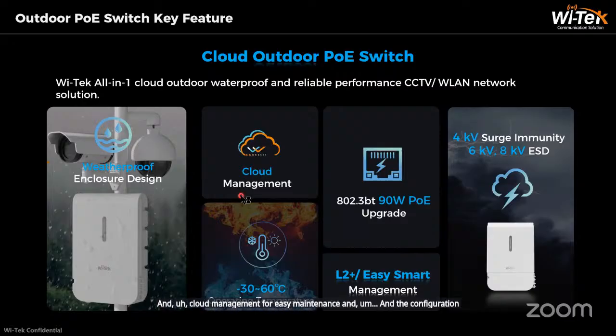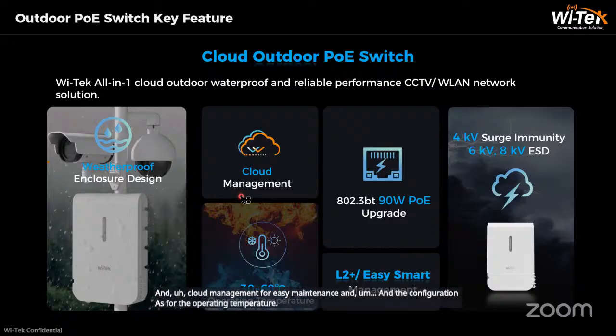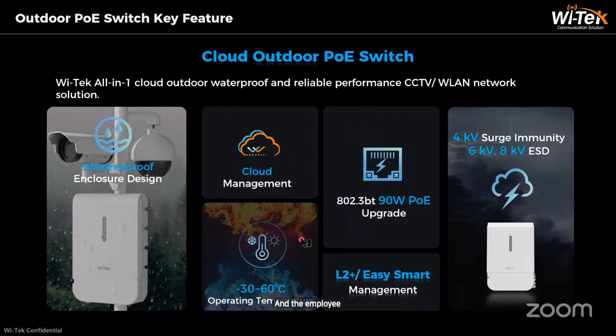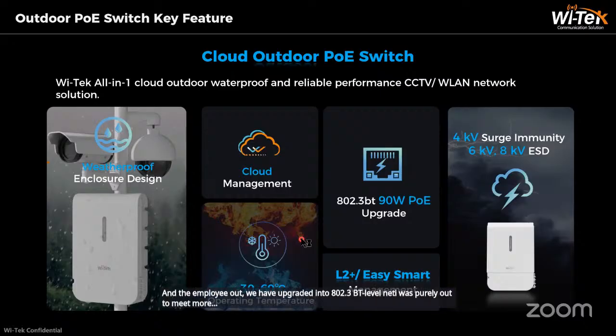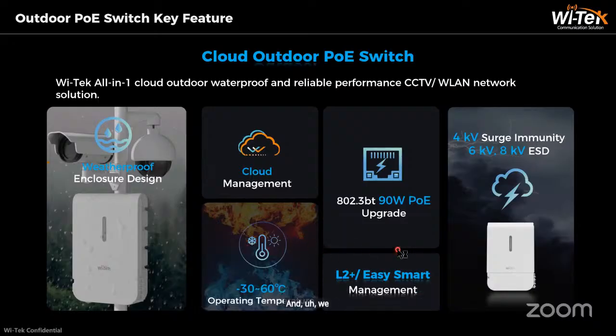As for the operating temperature, we offer -30 to 60 degrees Celsius. And for PoE output, we have upgraded to 802.3bt, level 90 volts PoE out, to meet the higher PoE power needs of terminals.